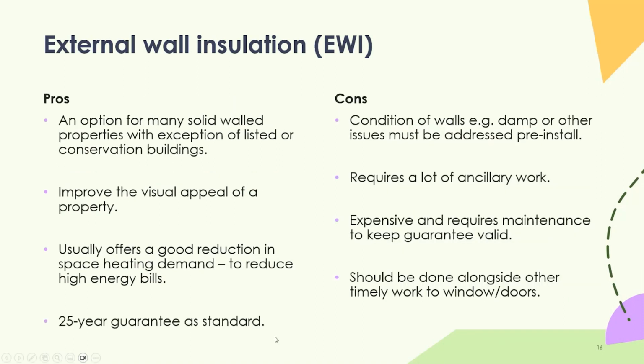Move on to the pros and cons of this particular measure. So first point there, it's one of the main options for solid wall properties, except where you have the building listed or in a conservation area, whereby the outside appearance of the wall, maybe the brickwork finish, or it might have some sort of ashlar or stone finish, is seen as culturally important and is to be protected. Therefore, you've got to look at insulating inside.